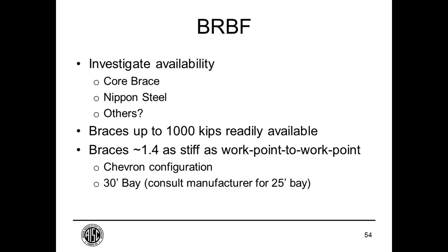Now, that 1.4 is appropriate for this particular condition that we're considering. For longer braces, say if you're doing a convention center and your braces aren't 20 feet long, but they're 40 feet long, that factor is probably closer to 1.2 or in that region. Or if you're using a very short brace or other conditions, it might be as high as 1.6 or 1.7. So that's why we're saying consult with the manufacturer or look at the literature. It's a function of the brace length and the force that's being transferred.